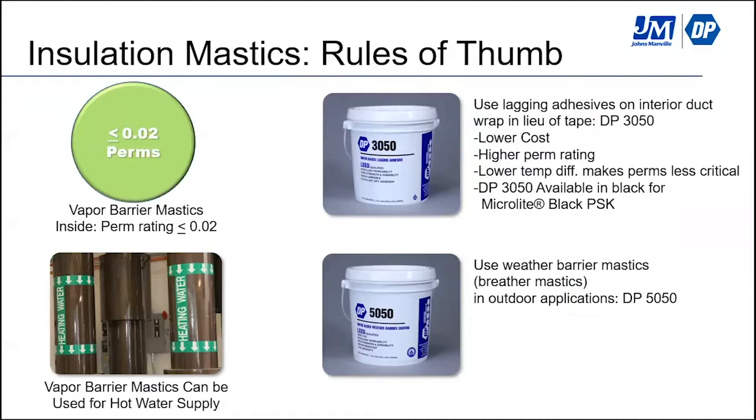You definitely have to use it with chilled water piping insulation. But most contractors will use the same product to seal all the pipe insulation, rather than having two different types of mastics and trusting that the right mastic would be used on the right system. And again, that's a general rule of thumb.